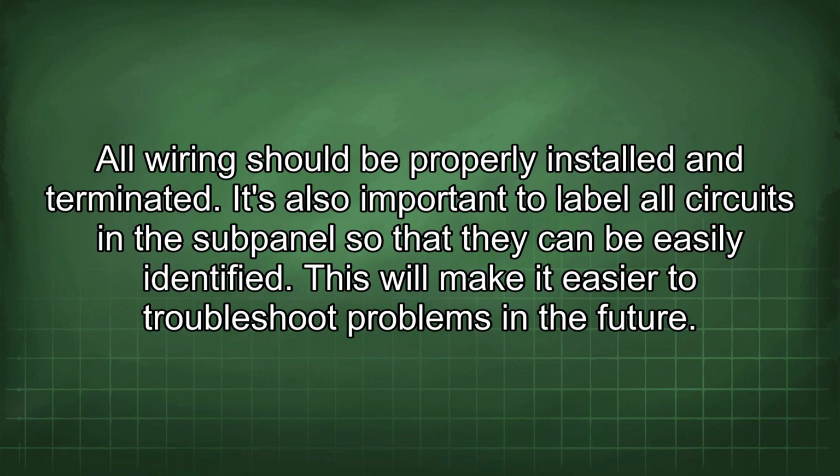It's also important to label all circuits in the subpanel so that they can be easily identified. This will make it easier to troubleshoot problems in the future.